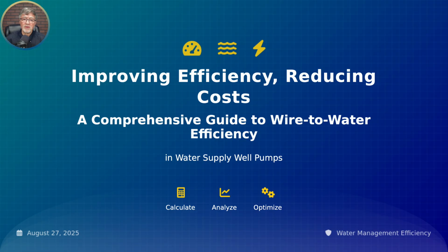And like all the things we do, if you've seen any of my other shows, you know I'm really big on calculating these trends, and that's going to be part of that with wire to water efficiency. You want to calculate that regularly and track it, because that's going to tell you when you're going to need to do maintenance or replacement on your pumps and motors.